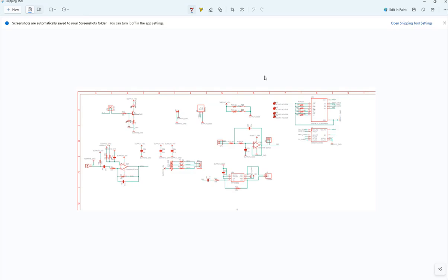So you have two buckets, right? When this bucket is being filled up by water, the other bucket was used for data acquisition before this. Now that one is full, and you are dumping the water from the other bucket to the SD card while this bucket is recording, and then next time you swap it. Since you cannot read and write from the same buffer at the same time, you have to use double buffering. This is for real-time data logging of a large amount of data at the same time. Super important technology, right?